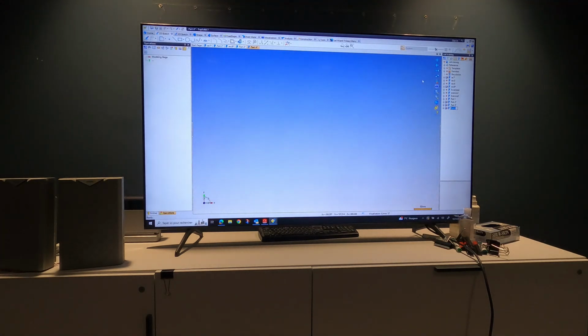So we just have to choose our heights on our Y. When you put the circle, you can define the position X, Y, and Z. So this is what we ask you. It's 0, 0 on X and Y, and the axis is a different level of the tape. Okay. Create a lofted surface.